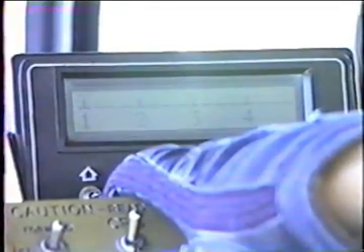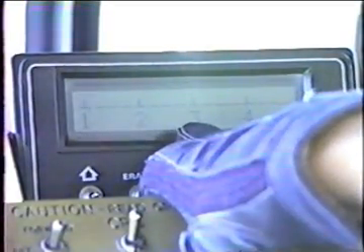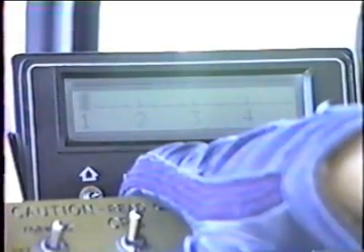If we don't have number 2 nozzles in the spray bar, then we've got 2 choices. Let's say that we have number 3 nozzles in the spray bar, and it's blinking on the number 2. Well, that's telling us that it thinks we should have a smaller nozzle in it than we actually have. So we should either speed up to get that to move over into the 3 position that we have in the bar, or if we need to run as slow as we are running, we should stop and put in number 2 nozzles.